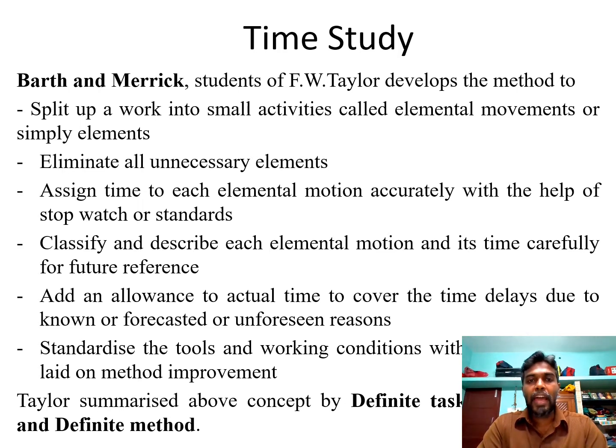Then Barth and Merrick, these two were the students of F.W. Taylor. They developed this time study method, in which they split up work into small activities called elemental movements or simply elements. They try to eliminate all unnecessary elements, and assign time to each elemental motion accurately with the help of a stopwatch or standards.